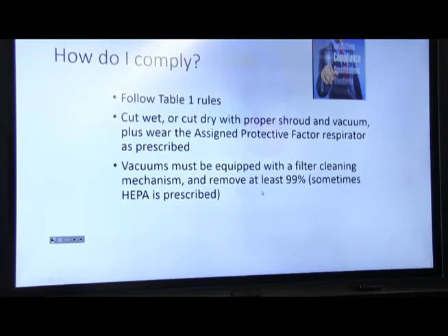Everything is designed to be cut wet, because if you add enough water to keep the dust down, then the hazard is also remissible. So we don't even have to use the engineering controls if you can do this task wet. But if we can't do it wet, which a lot of times if you're using an electric drill, it's not a very good idea to do a wet cut unless it's designed specifically for that purpose.